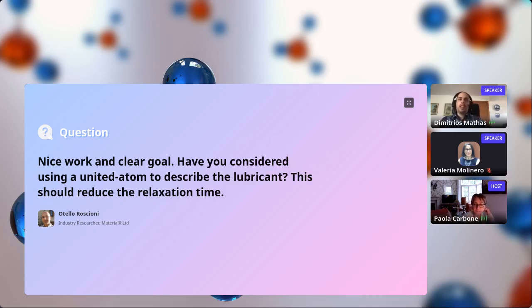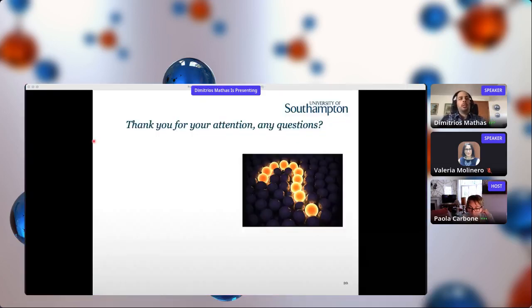Right, thank you for your question. We haven't tried the united atom, although some initial papers that I've read compared different available force fields for lubricants, and this paper from UCL in 2016 made a comparison of different force fields, and the united atoms didn't perform very well for calculating the density as well, not only the viscosity.